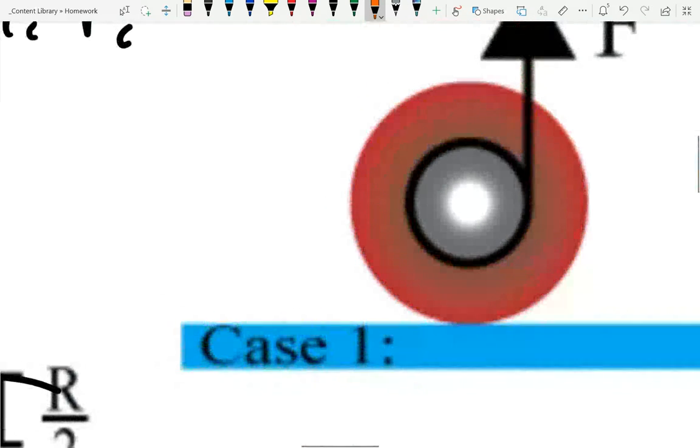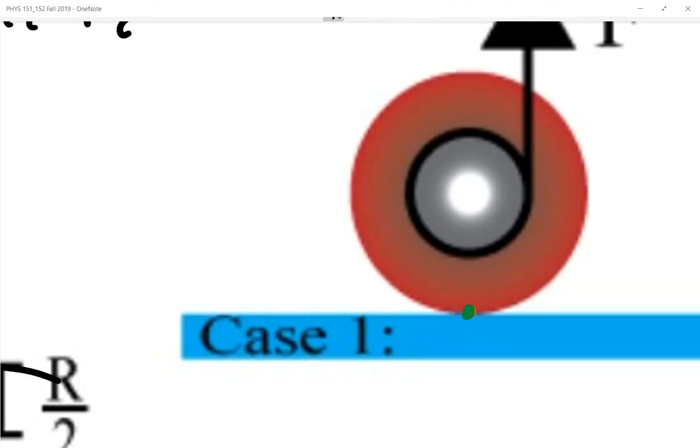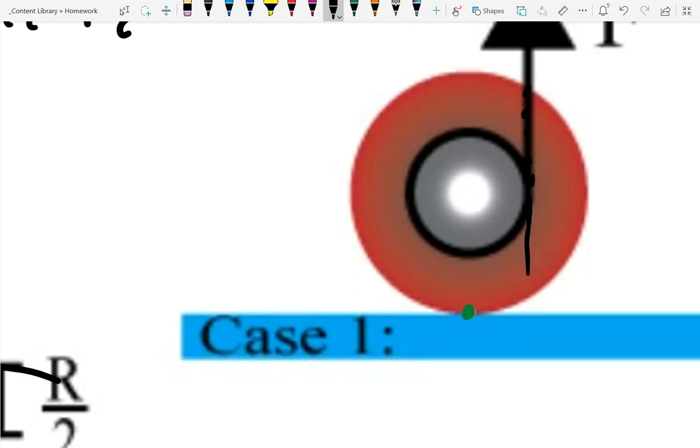So it says for both cases, so we look here. Again, summing the torque about that point. And now what's my perpendicular distance? I take this line of force and I just extend it. The shortest distance, the one that's perpendicular, is this distance right here.